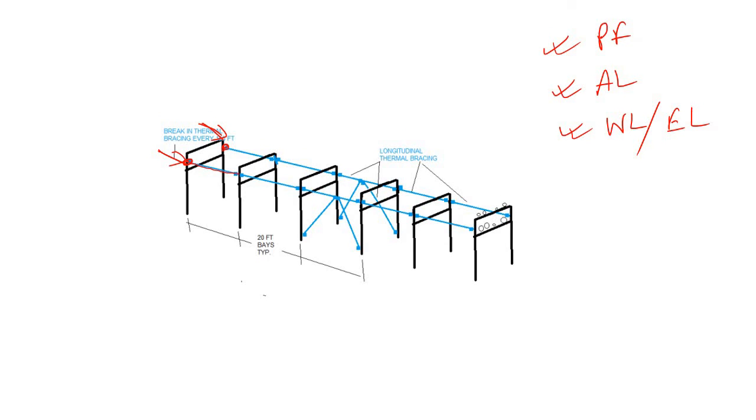Then they travel through this strut beam and come to this nodal point where the bracings are met. So if you consider this lateral load, it travels through this beam, then comes to this joint, then travels through this strut, comes to this joint, then travels to this nodal point where these two bracings are meeting, and then from this nodal point it will travel to the foundation which is nearest. So in bracing, simply the lateral loads are being transferred to the foundation.